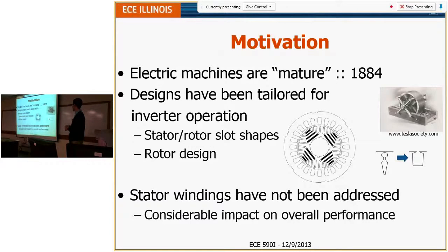So here the rotor is going to expand outwards, and here it's not going to expand out as much. Whenever you have one part expanding more than the other, you get lots of vibrations and more pressure, and your reluctance is changing, and it gets really messy. So it's really a mechanical analysis that sets the speed, not the electrical. I mean, maybe the inverter will, like the switching losses, but it's mostly mechanical.